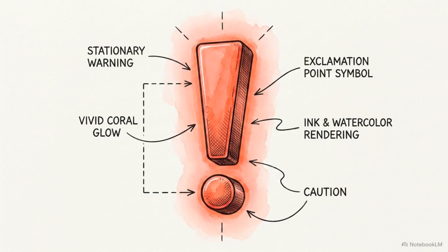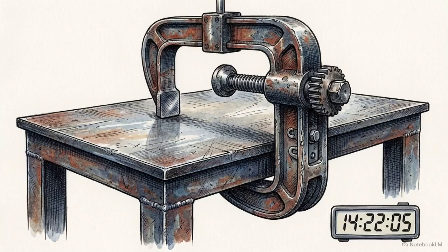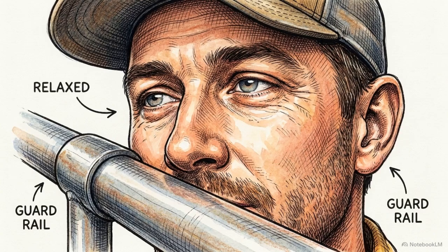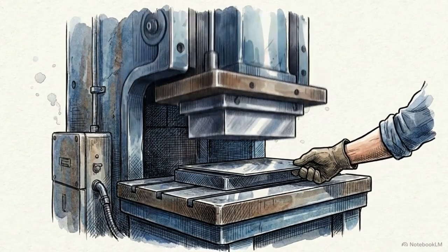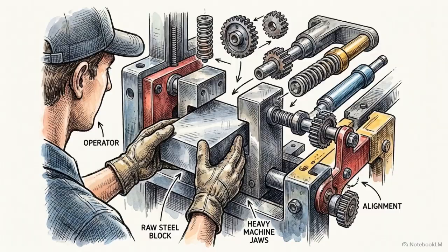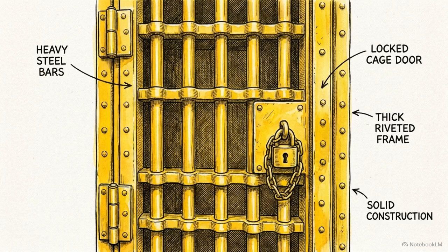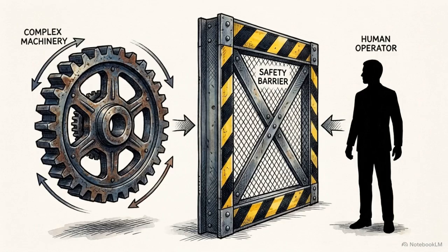The point of operation often carries a hidden, specific danger: intermittent motion. Unlike a continuously spinning gear, intermittent tools sit completely motionless for parts of the production cycle. This static state tricks human muscle memory. An operator becomes comfortable, forgets the hazard is live, and the machine unexpectedly actuates to clamp. Because the point of operation requires a human to load material close to the hazard, it demands the highest density of engineered protection. Safeguarding is the process of physically and systemically decoupling the human operator from those identified hazards.